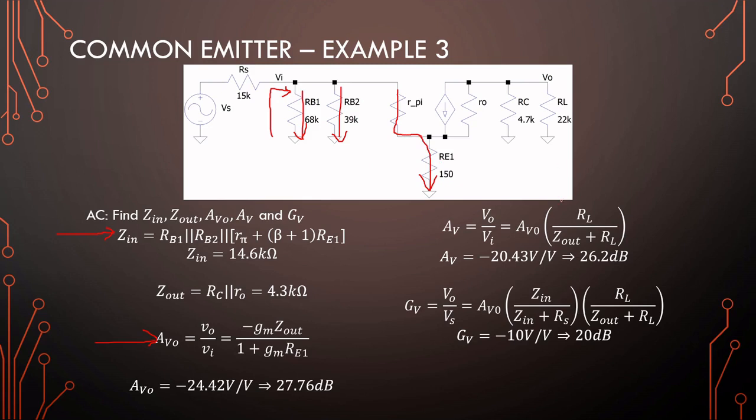Right. When doing the small signal model, I said it's important to replace a small x right here on the model. So anything that we see beyond this transistor will look larger because the current on this side is IB and the current on this side is IB multiplied by beta plus 1. So the same goes for any impedance on this side, for the base side it will look beta plus 1 times larger.